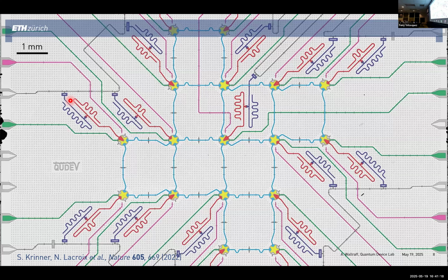Good, and then you see these red resonators. Daniel has talked about readout of superconducting qubits. So these are lambda quarter resonators that are strongly coupled to these qubits, and you look at the frequency shifts of these resonators when the qubit changes state. From this dispersive Jaynes-Cummings Hamiltonian, you see that the resonator inherits a qubit-state-dependent frequency shift that you can read out to determine with good fidelity, or low error, the state of the qubit.